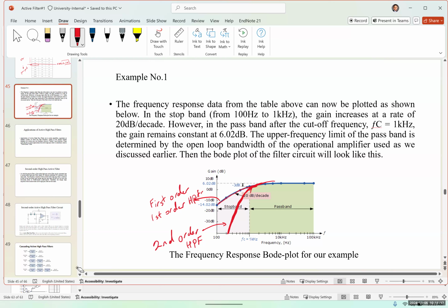An ideal high pass filter would actually look like this. You're going to have a cutoff frequency, and it's going to have like a square filter like this. This is an ideal. Obviously, we know we never have an ideal high pass filter. And when you have something that is very high order, you're going to have what we call overshooting, meaning that changing from this, you're going to have a little bit of overshooting. You're going to probably learn this in signals and systems.